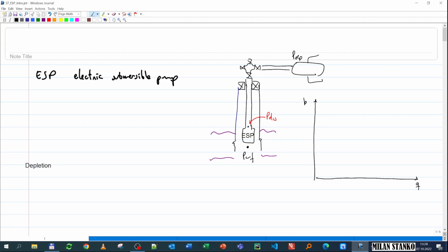Typically, when we have electrical submersible pumps, we're talking about oil wells that produce oil and liquid and water. And typically it's under saturated reservoirs, although I could also be producing from saturated reservoirs if the gas amount is low. But we're going to make an IPR for this case, like if it's a linear IPR, corresponding to a saturated, undersaturated reservoir. So that's the IPR. That's the curve seen from the reservoir, how much pressure is available at the suction of the ESP, and that is the PWF.